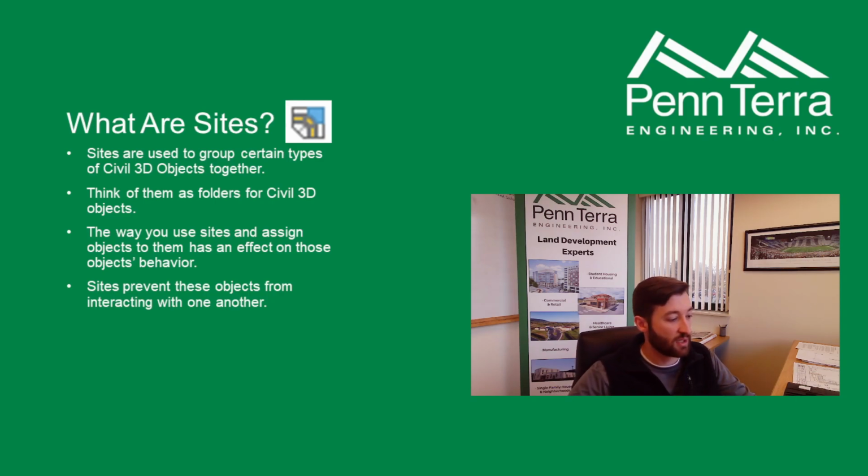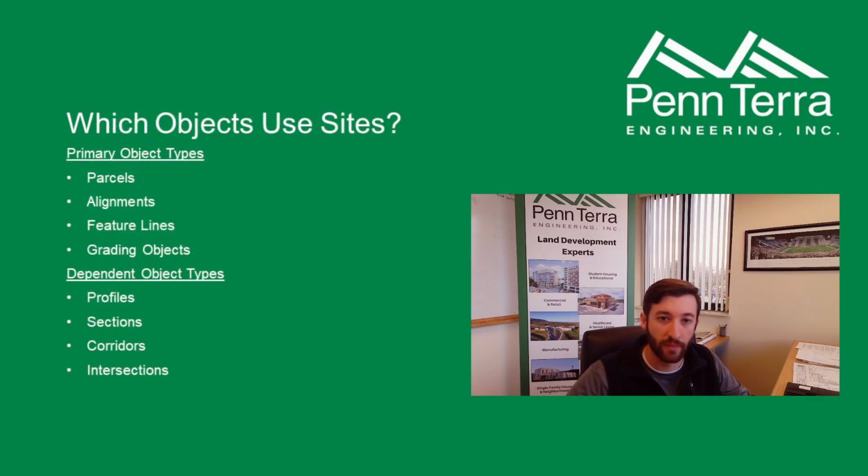So what are sites? Sites are used by Civil 3D to group objects together, intelligent civil objects. So I like to think of them as folders. And you have to assign certain types of objects to a site. Otherwise, they can interact with one another and potentially cause issues, which we'll look at here in a little bit.